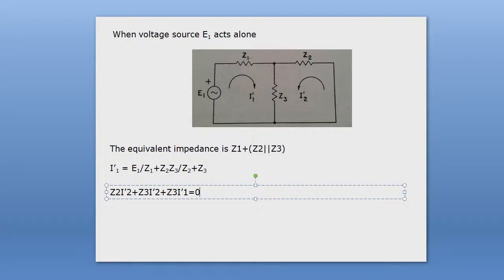Everyone, use the concept of mesh equation. That means you use the voltage law, KVL. The total voltage drop across a loop is nothing but the sum of voltage drop for individual elements associated with that particular loop. So for this loop, you see there is no supply voltage. If there is a supply voltage, then this algebraic sum will be the same as the supply voltage. So therefore we can write